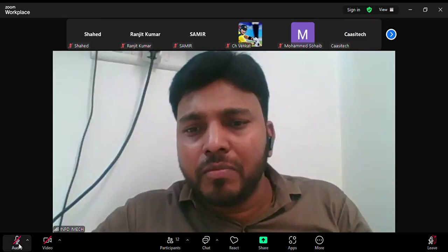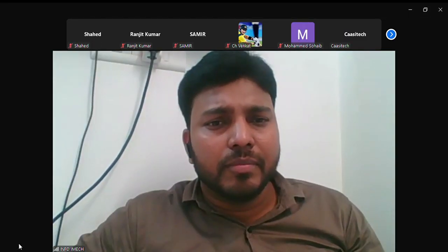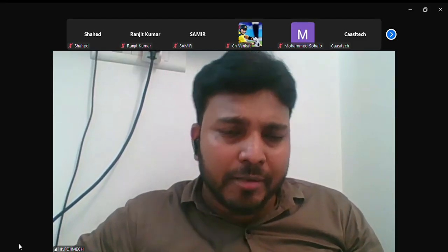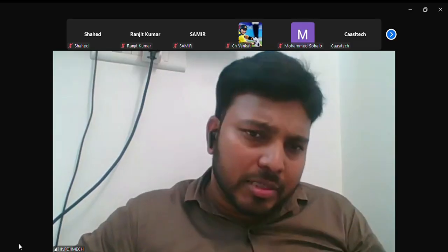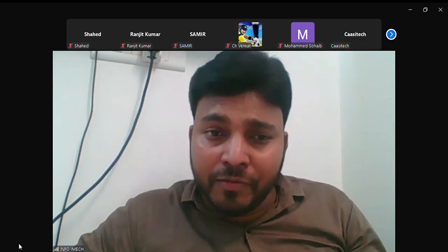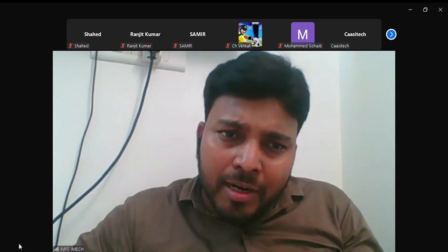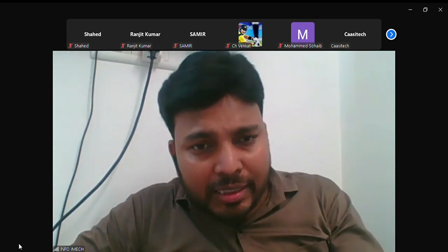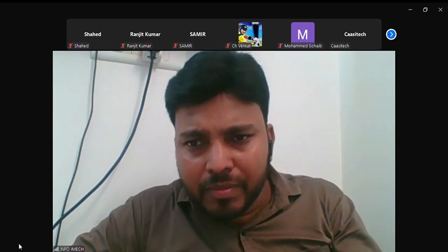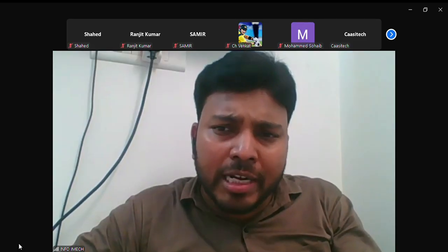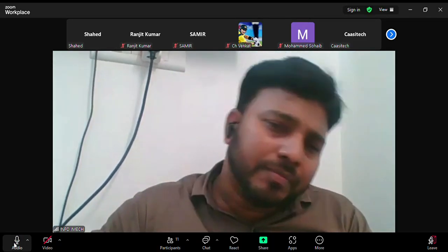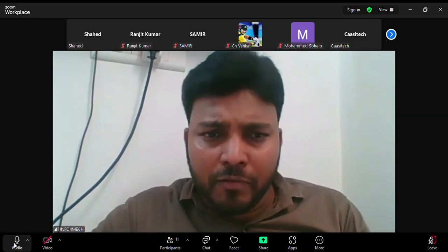So that means at the depth of 6 centimeters, the machine should display two echoes, guys. One is the back wall reflection, another one is the defect reflection. But the back wall reflection height is 30, the defect reflection height is 7.5. In these two, which echo height will be more? The back wall echo.